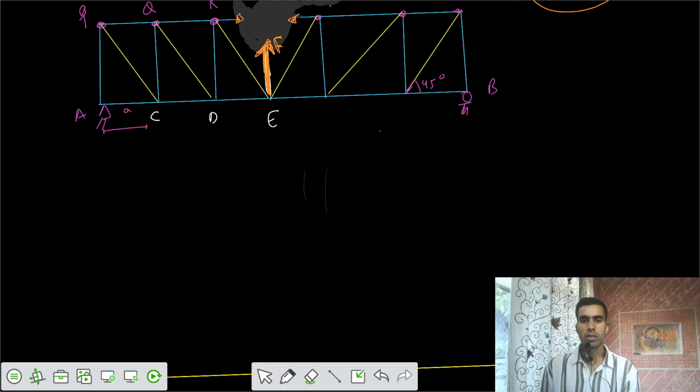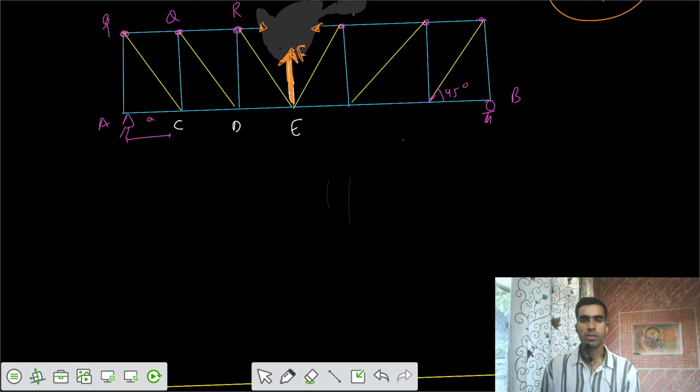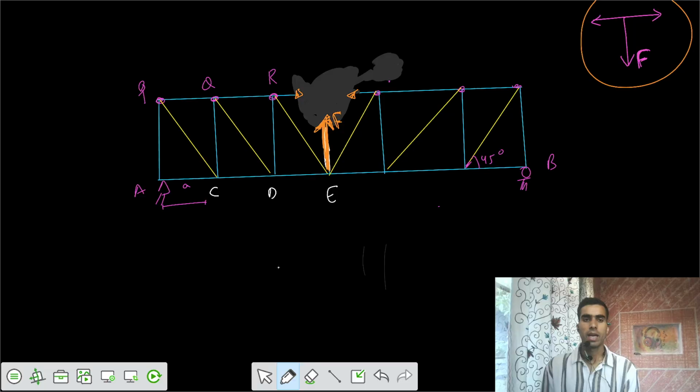Now for this one you have this ILD reference line. I would say let's place the load at the first location of B. What is the reaction we have? Can you tell me the reactions? Because we are cutting the section, we have the entire structure also. When the load was placed at this location, unit load of 1, the reaction developed is equal to 1. Okay, reaction is also equal to 1. So what is the reaction here also? That reaction equals 0.